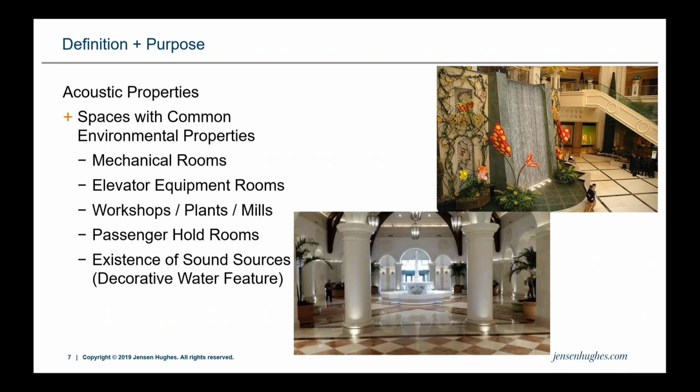And maybe even more difficult or challenging spaces. This is a picture, back when we all could travel, of the JW Marriott in Orlando, Florida. Very, very beautiful facility, but you see the hard terrazzo tile, marble type flooring, marble columns, marble tiling on the walls. It's very high, a lot of volume, very difficult acoustics in this space. This space was actually provided with 4 regular fire alarm horn strobes. It would be very, very difficult to provide intelligible voice inside a challenging space like that.